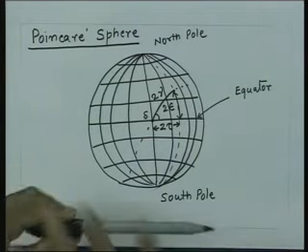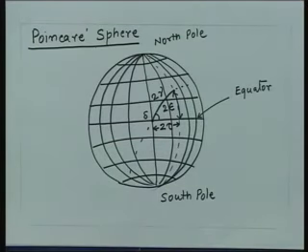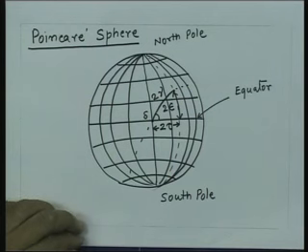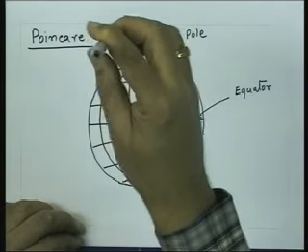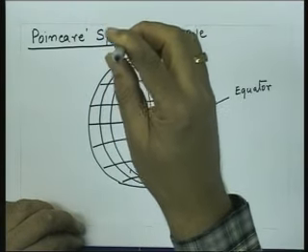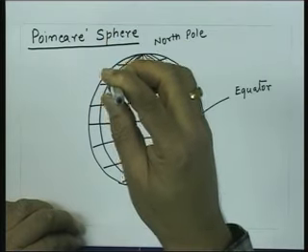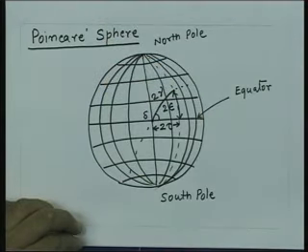So, if I start on this globe, if I start from here, the reference point, the line was horizontal. As I move, the line slowly tilts like that, and when it goes back of the sphere, the line becomes vertical. So, on the equator, the reference longitude point represents a horizontally polarized wave, whereas on the equator, if I take the diagonally opposite point, that point will represent a vertically polarized wave. Again, as I move further the angle will go on tilting, and when it comes back, the line has become again horizontally polarized.